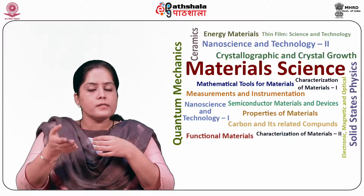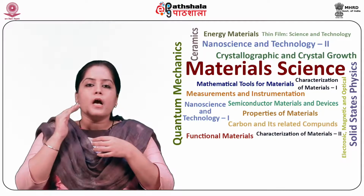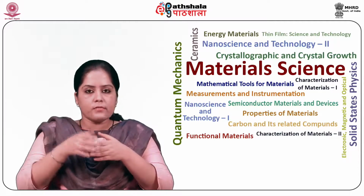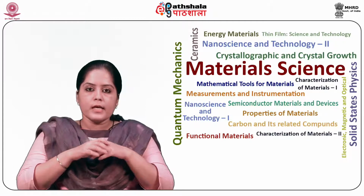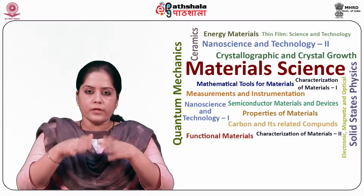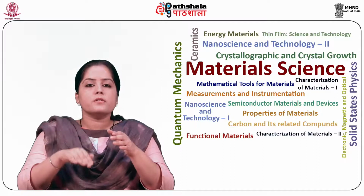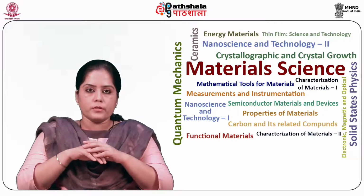The next one is remote plasma enhanced CVD, RPECVD. This is similar to PECVD, except that in this the wafer substrate is not directly placed in the plasma discharge region. This has a benefit that we can reduce the processing temperature down to room temperature.